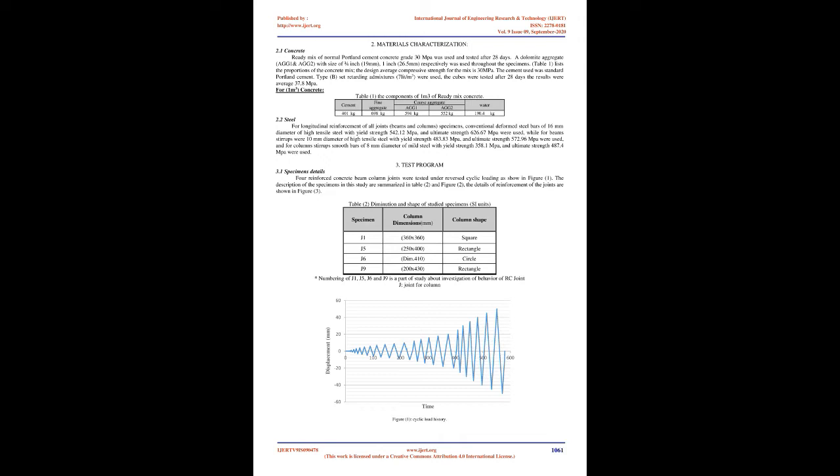Most studies on the behavior of reinforced concrete, RC, beam column joints focused on effect of concrete grade, different aggregate type, longitudinal reinforced bars and columns, transverse reinforced ratio. Ramadan M.A. et al. studied performance of external reinforced concrete beam column joints made of high-strength concrete using 26 specimens. The main parameters were the details, type, and amount of joint reinforcement, the type and amount of beam and column main reinforcement in the joint. The results showed that increasing the concrete compressive strength leads to an increase in the joint shear resistance and deformation capacity.